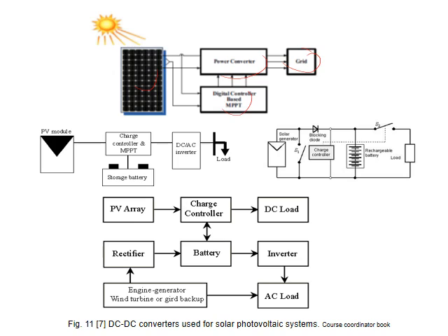This is another block diagram representing the PV charger controller. They call it the charger controller, and MPPT, maximum power point tracking, where the DC-DC converter here could be step up or step down. We may provide some part of the power to the storage battery, and some part will go to the inverter. We will explain the inverter soon, to convert it into AC and inject it into the grid or to the load.